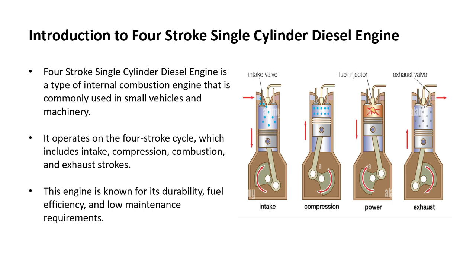4-stroke engines have 4 strokes per combustion cycle. That means in order to fully complete a combustion cycle, the piston is going to need to move down once, up once, down once, up once. That's the 4 strokes, and each stroke has a purpose.